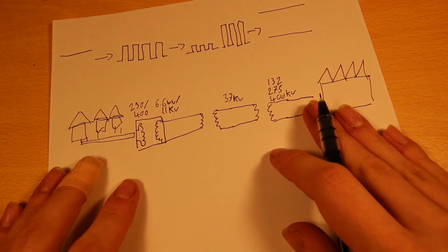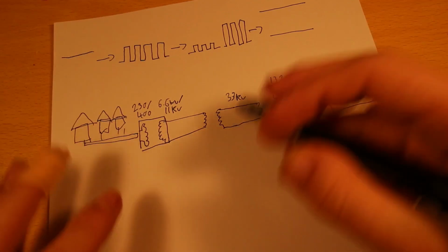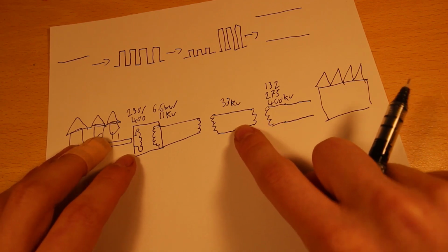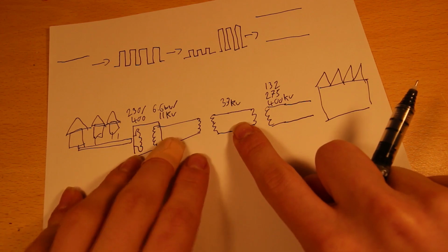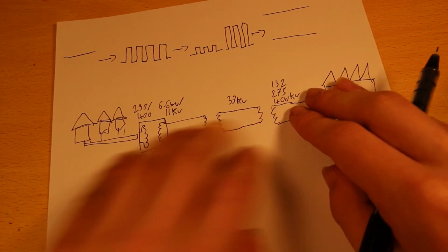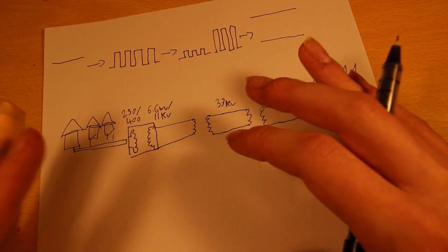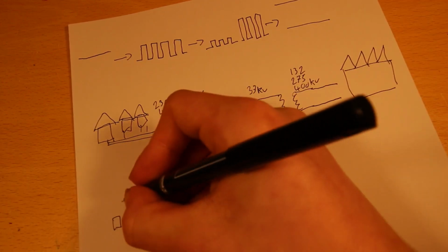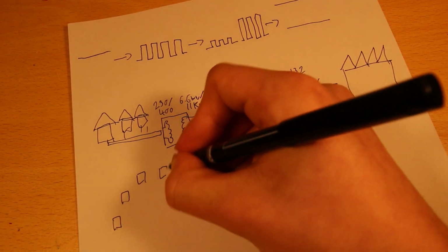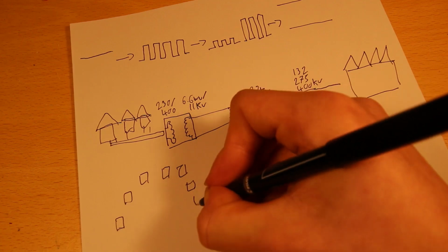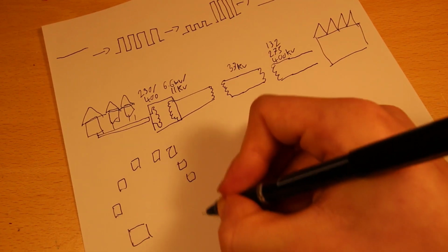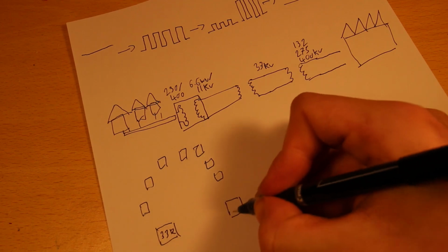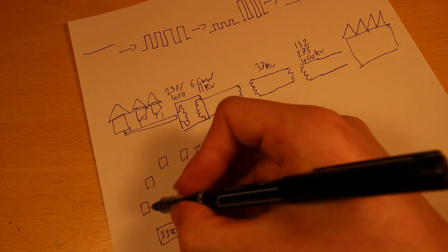But this is the basic setup. Usually there'll be spurs off all over the place where things like this 400 kV line will probably feed loads and loads of 33 kV stations, which will each feed loads and loads of 11 kV stations, and they're not wired like this. They're usually wired in discontinuous rings, which again is a technicality. Basically what that means is your substations are these boxes like this, and then you'll have a big substation here and a big substation here. So let's say these are 33 kV substations, and each of these ones here are 11 kV.